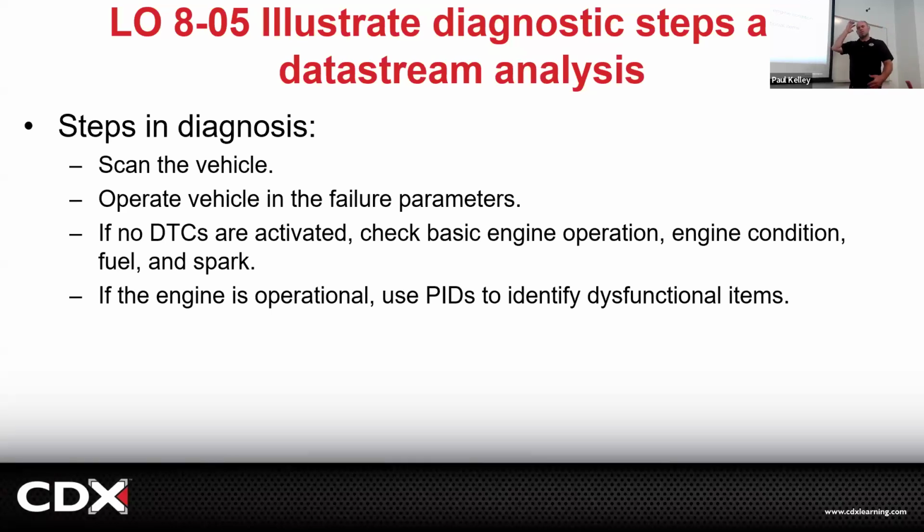So check the codes, and honestly, if it's a misfire, if it's a P0301 and I start the car and I see the engine shaking, I'm pulling it right straight in. I'm like, look, it's happening right now. We're good. I like when problems are active and they're apparent. The problem is, it's got a P0301 and then I run it, and it's like, hey, it's looking pretty good. I don't really see an issue.